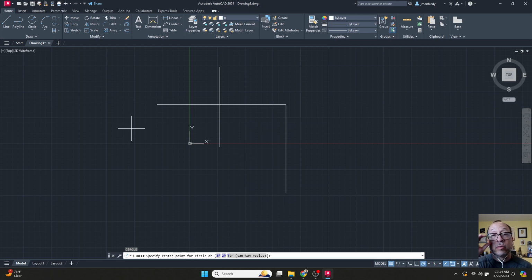Normally, you can just pick a point in space, but if I had to be very specific about where I want to draw the circle, I would take my cursor and hover over the end of something, and the O snap gets turned on. First, you get the little symbol, and as you get closer, it gives you the name of the O snap. The center of the circle will jump to that specific location that's green currently. It's very, very precise. Click, and it's active. So when you see the icon appear, it'll launch that O snap and put the circle exactly where you want it to be.